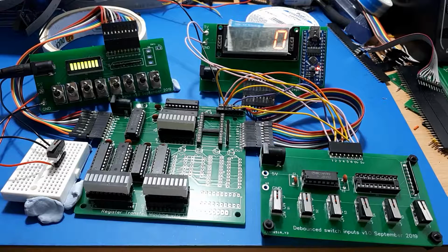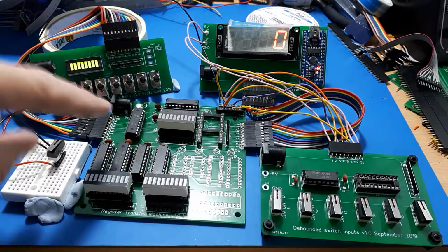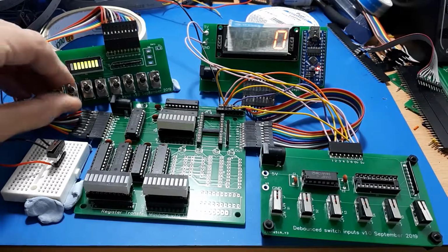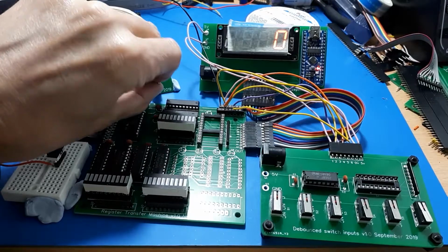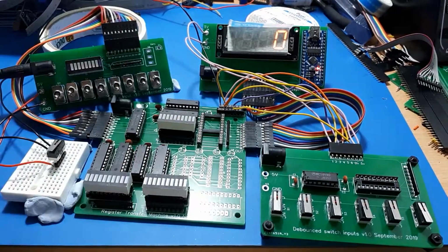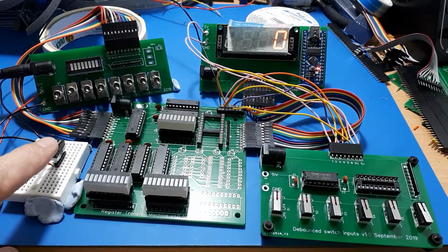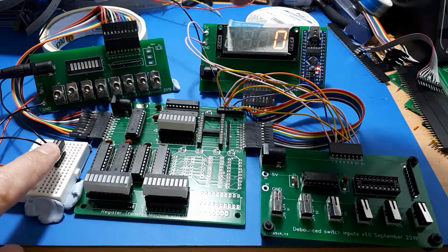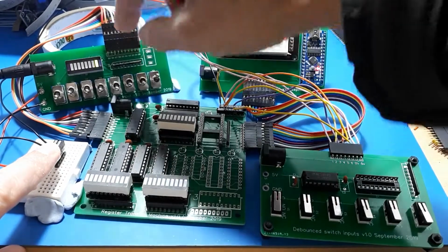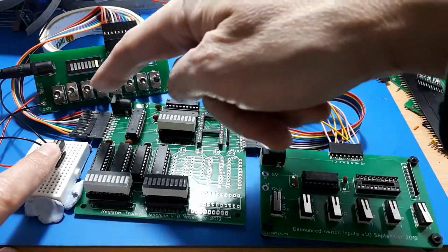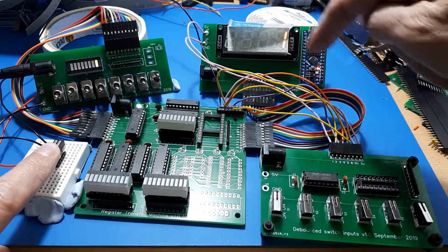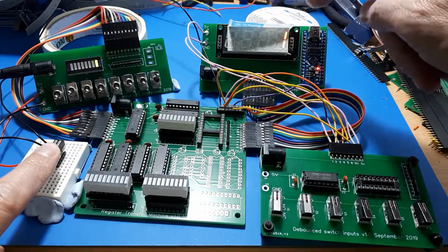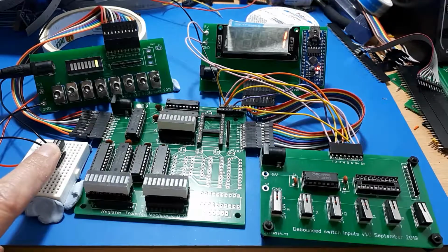Okay, so having explained all that, I've got here my register transfer machine set up to do some register transferring. I've got the keyboard on the left here. This keyboard is my 8-bit binary keyboard, and that shows a binary number. I've got a switch down here which publishes the binary number onto the bus. So if we put a 1, we get a binary 1 there. It goes onto the data bus of the register transfer machine, straight through and out the other side. And I've got my binary to decimal display plugged in on this end, so we see a 1.